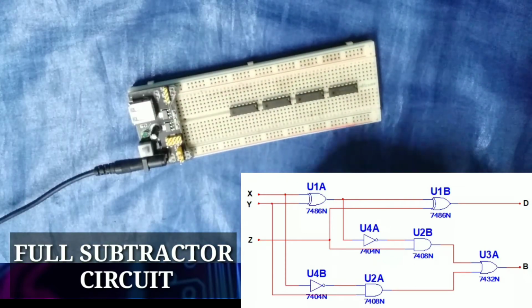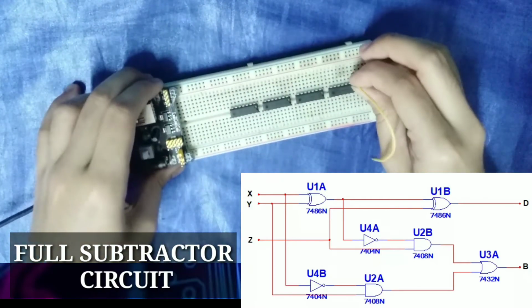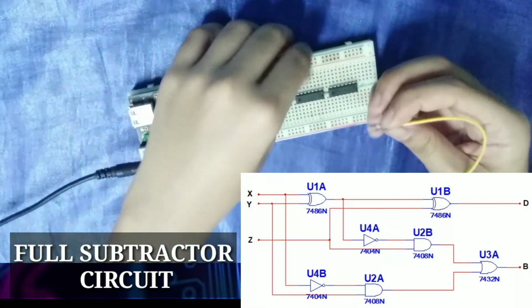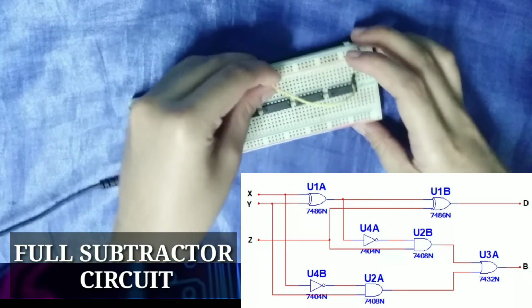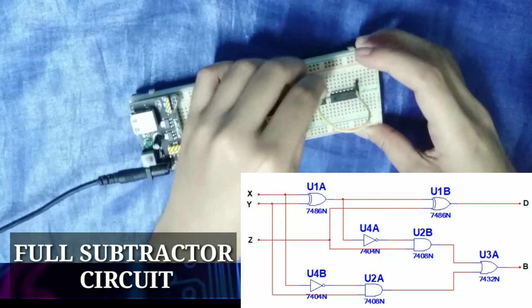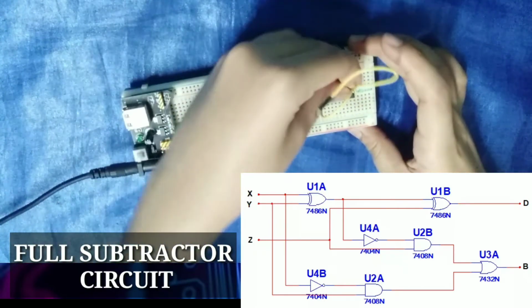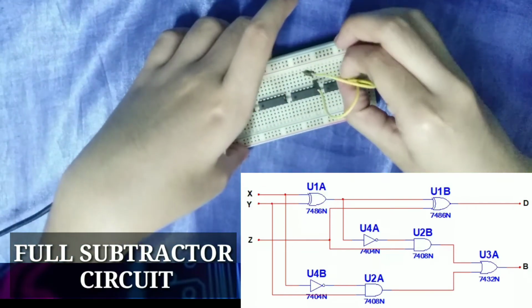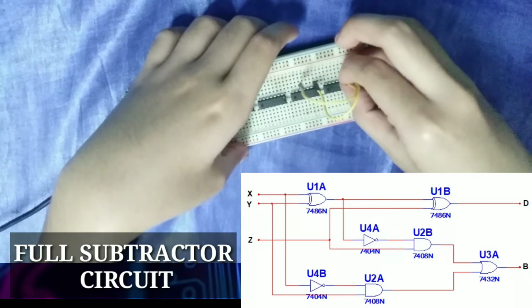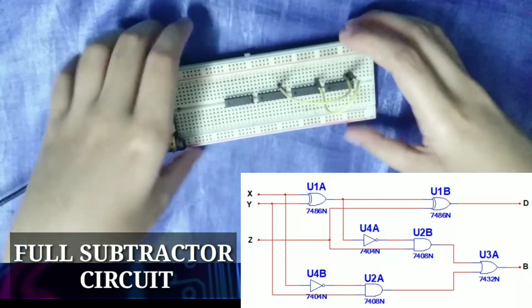Now, according to the circuit diagram, let's connect pin number 1 of the 7486 to pin number 1 of our 7404 IC. So here. Now, let's connect pin number 2 of the 7486 to pin number 2 of our 7408.